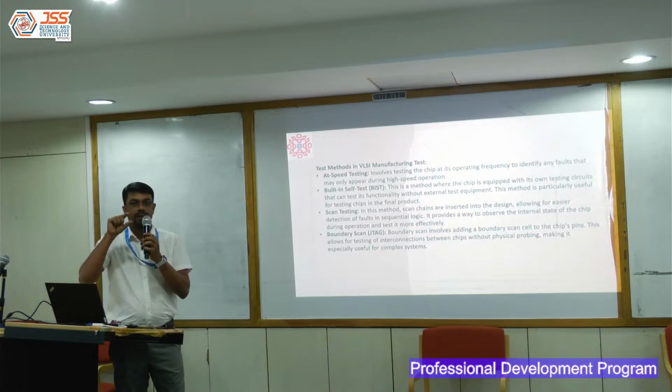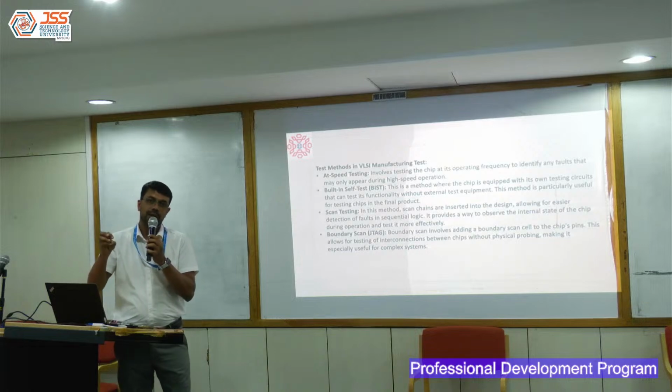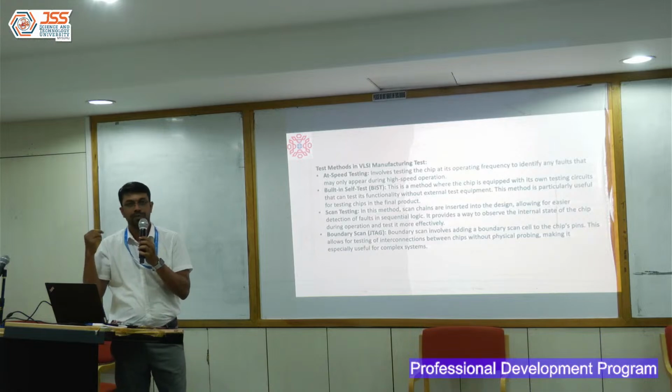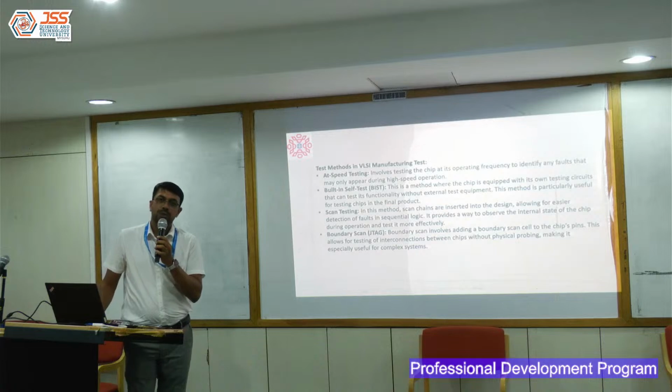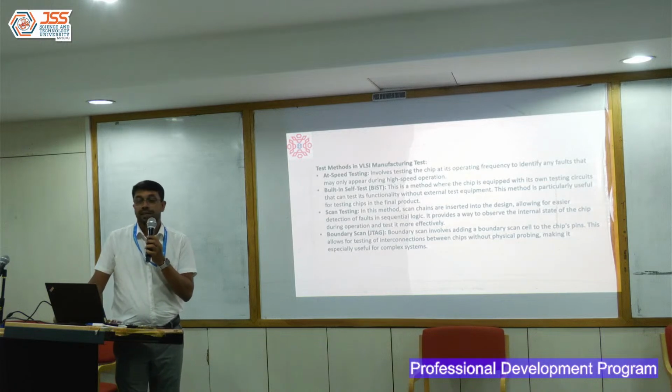They will be very slow or low frequency clocks, typically 10 megahertz to 50 megahertz, or sometimes even 100 megahertz or 400 megahertz. But it's definitely less than your functional clock. So it has to select between these two clocks. And this is where all the concepts of setup and hold come into picture from the testing point of view.